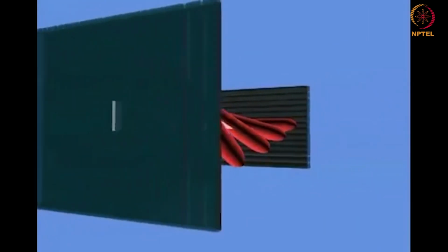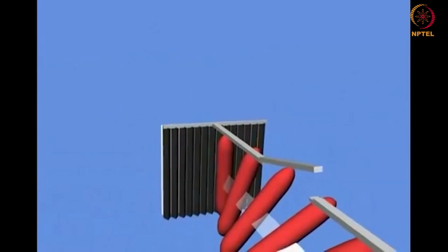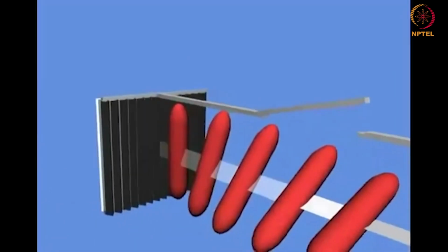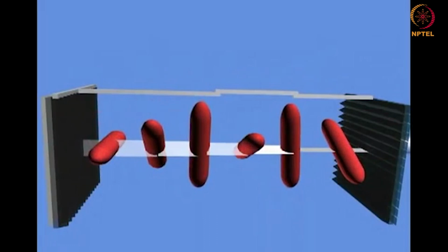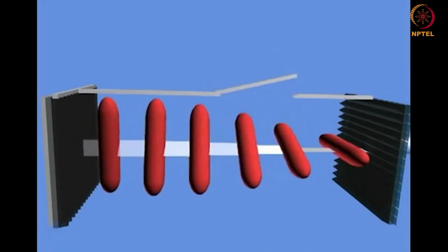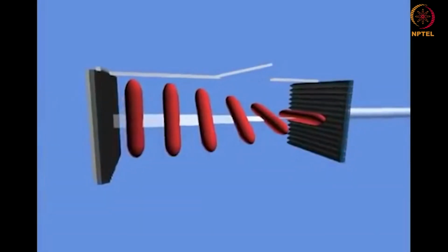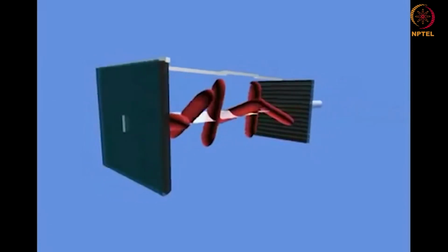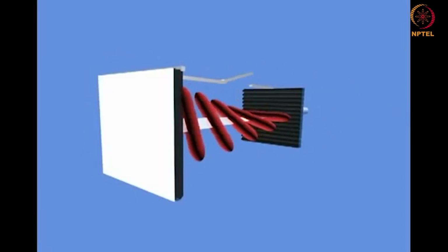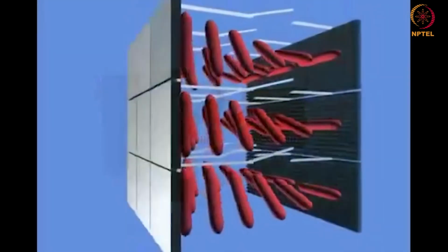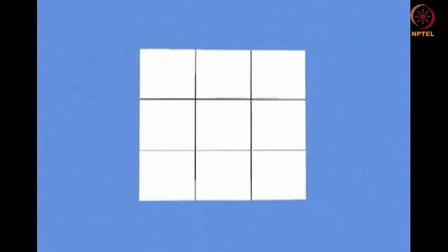If an electrical field is then generated between the glass plates, the special property of the liquid crystal molecule becomes fully apparent. As the molecules are dipolar, they react to the electrical field and are repelled. The rotated molecule structure is interrupted. When light then passes through the first polarization filter and follows the direction of the molecules, this hits the outer polarization filter and cannot pass through it. When a matrix is created from a number of these individual cells, it becomes possible to display graphics and images.